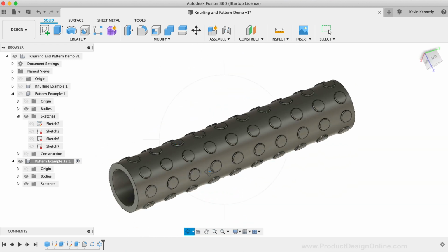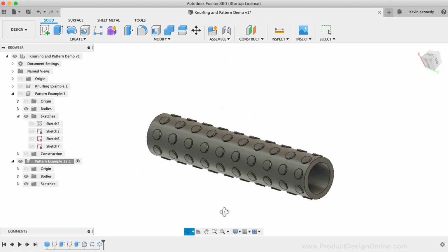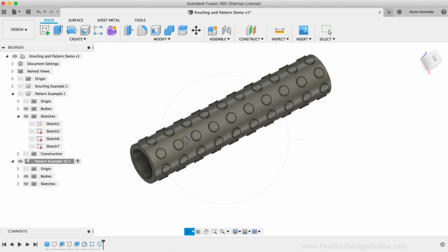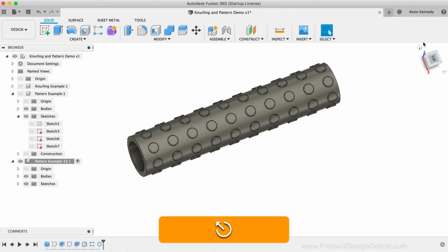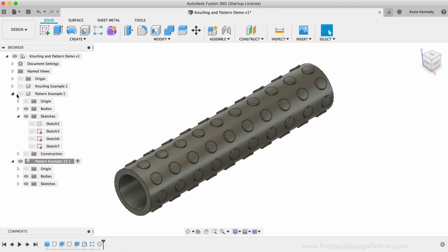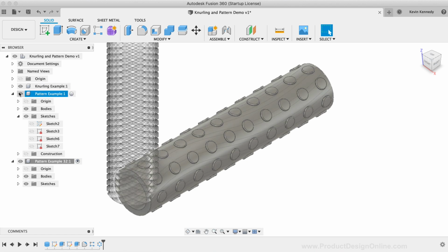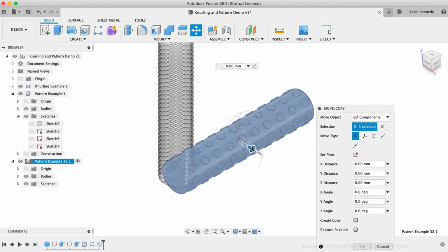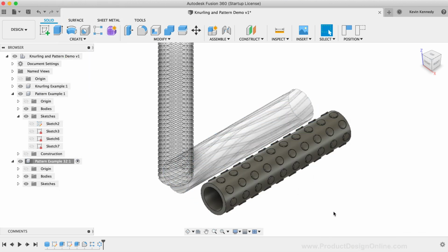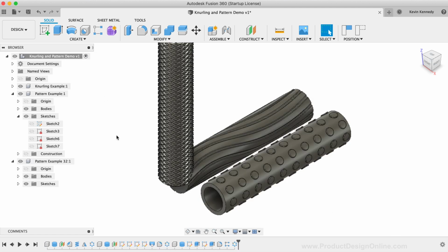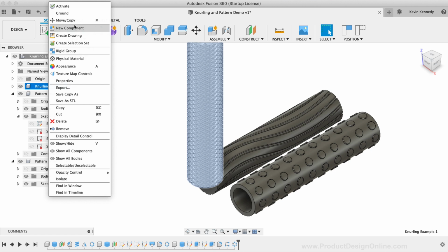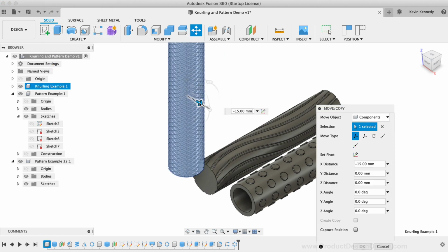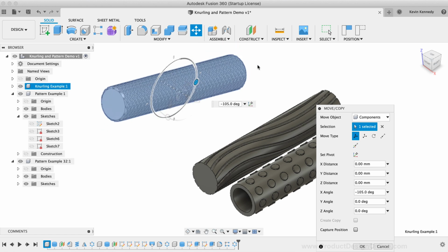To wrap up this tutorial, there's one last important thing to note. You'll notice the patterning tools are pretty resource intensive in not only Fusion 360, but any CAD program. This is because the program will have to process the details of each and every single patterned object. If you're going to have patterned objects in larger assembly models, then one tip that you'll find to be helpful would be to put the pattern part in a separate file and then insert that file back into the assembly file. That way, if you need to update or alter the pattern or its file, then the file will run quite a bit faster as it won't have to process all of the other components.